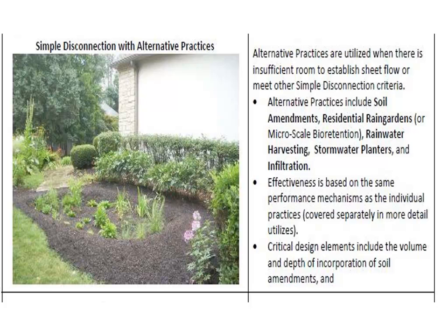I'm not certain on an absolute quantitative basis how much having plants versus not having plants helps. It's interesting, in stormwater management, they have a series of credits. The regulators don't look at it on an absolute basis either, trying to measure the actual water uptake of a certain plant. They'll say that you get credit for taking certain measures. As long as you get to a certain reduction in volume, they don't care how you achieve it necessarily. But you can save a lot of money by putting in natural features like this.